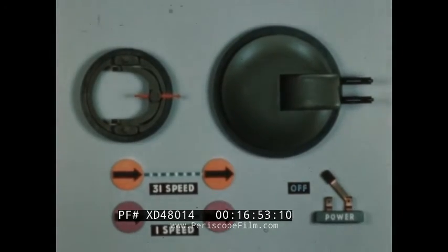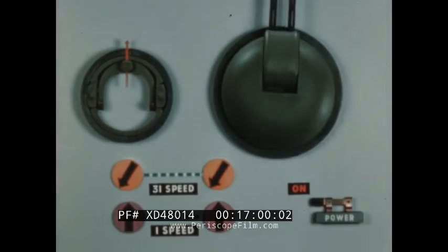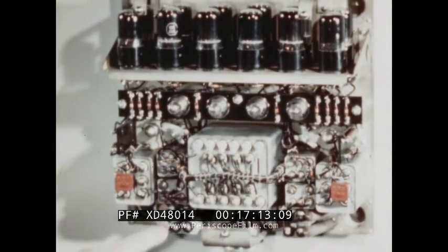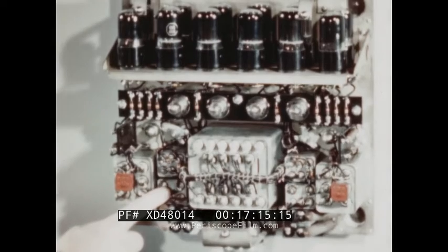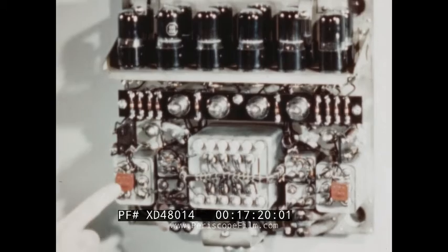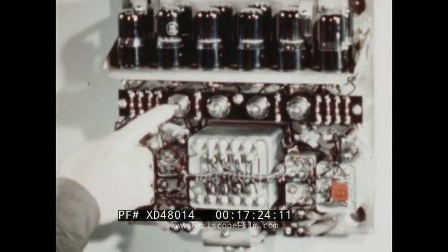Again, with the power off, the sight is moved. Switching on the power, the guns are now driven until both Selsyn receivers are aligned with their respective transmitters. The guns and sight are now in alignment. The one-speed signal is amplified by the signal input transformer, a double vacuum tube, condenser, output transformer, and 2 neon lamps.